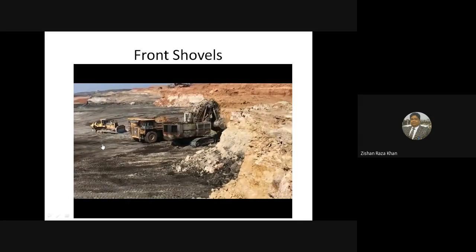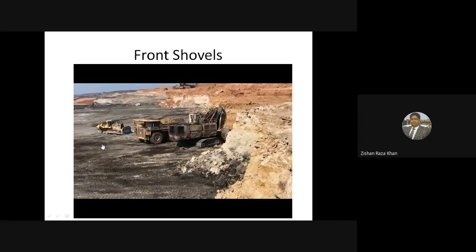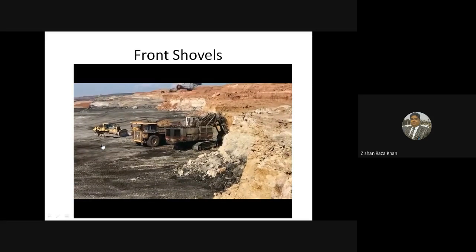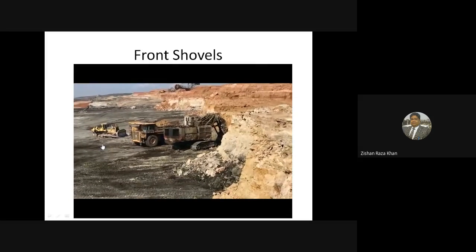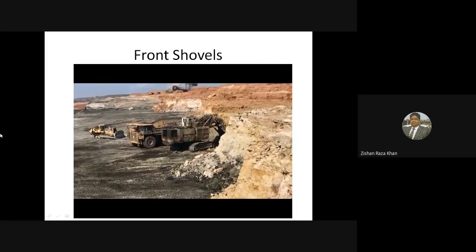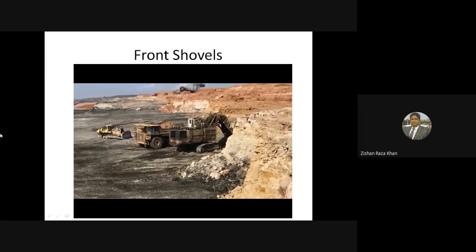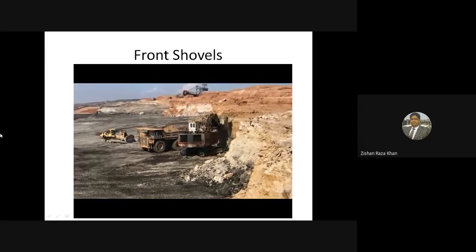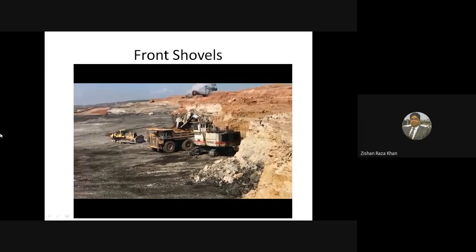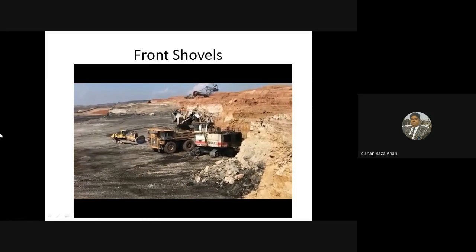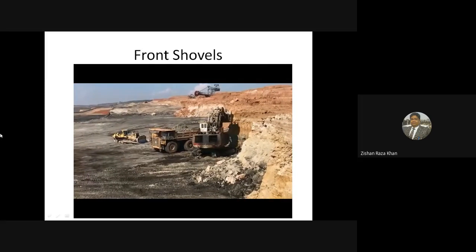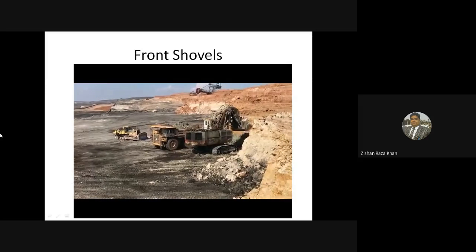This will create a deficiency in the process, wherein the last fifth bucket is not fully utilized, and that cycle time will not produce the desired output completely. So, effort should be made in such a way that the truck should take the full bucket capacity, as you are seeing in this operation.